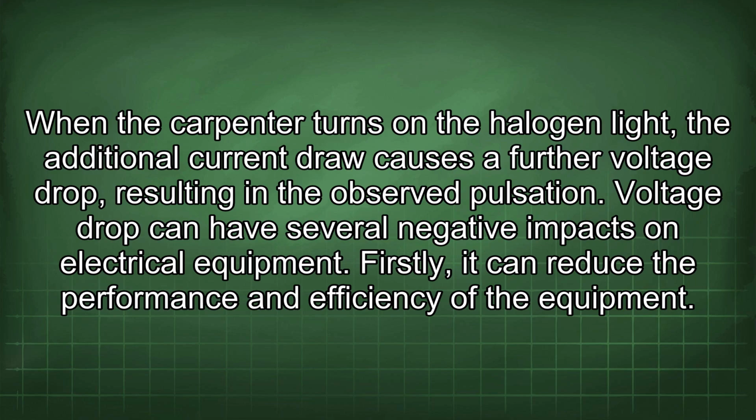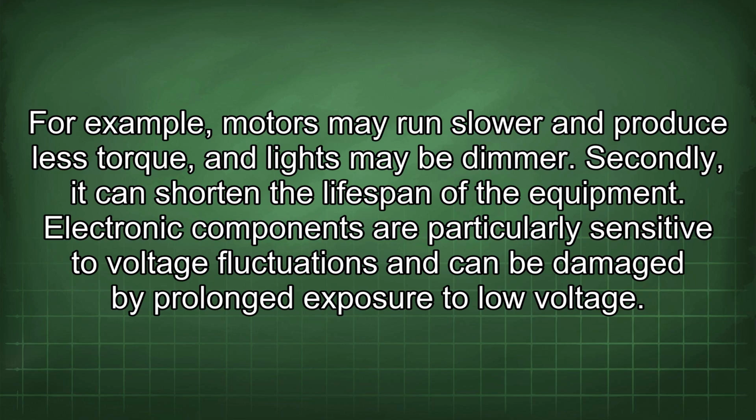Firstly, it can reduce the performance and efficiency of the equipment. For example, motors may run slower and produce less torque, and lights may be dimmer. Secondly, it can shorten the lifespan of the equipment. Electronic components are particularly sensitive to voltage fluctuations and can be damaged by prolonged exposure to low voltage.